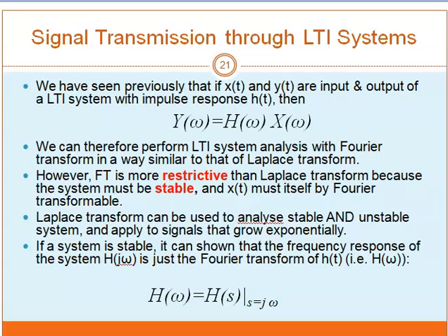We have seen previously that if x(t) is the input signal and y(t) is the output signal of an LTI system with impulse response h(t), then we have this equation: Y(ω) is equal to H(ω) times X(ω). Therefore, we can perform LTI system analysis with the Fourier transform in a way similar to that of the Laplace transform.